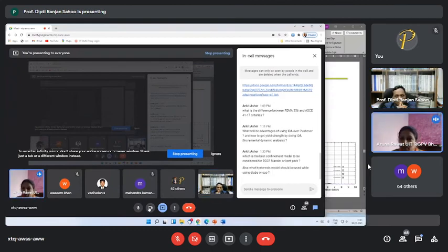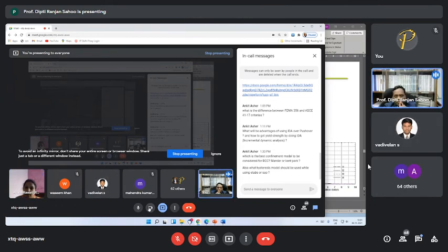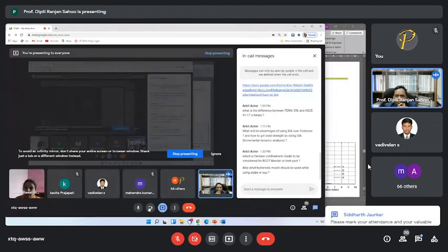There is one question, sir. What is the best confinement model to be used? Yeah, I have that answer. You have the hysteresis model for the concrete. I think the Takeda model is for the concrete, and if you are following structural steel, I think combined hardening, or maybe kinematic or isotropic hardening, should be fine.